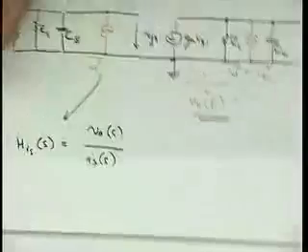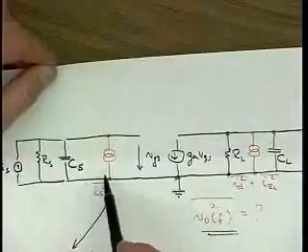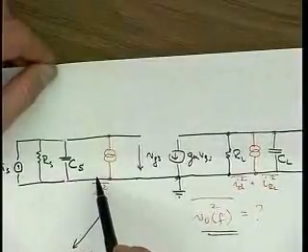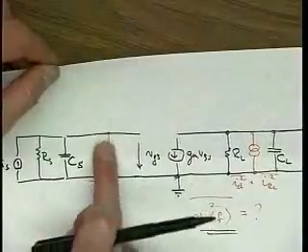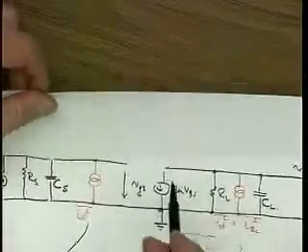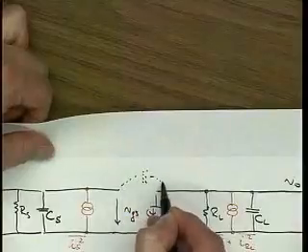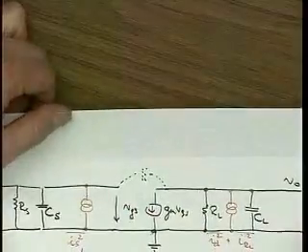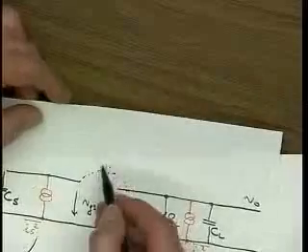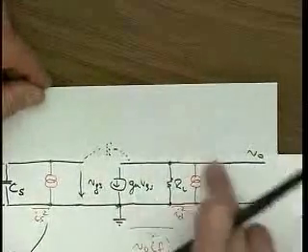And then at higher frequency, of course, this noise current source experiences filtering. First, it experiences a pole produced by RS and CS. Then, in principle, it also has a coupling capacitance here, the CGD, and then it sees another pole.